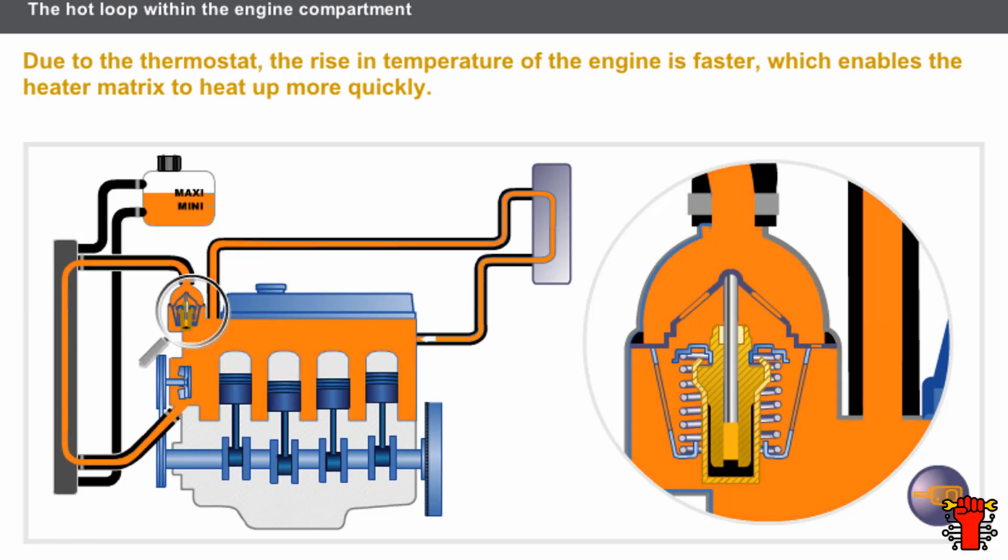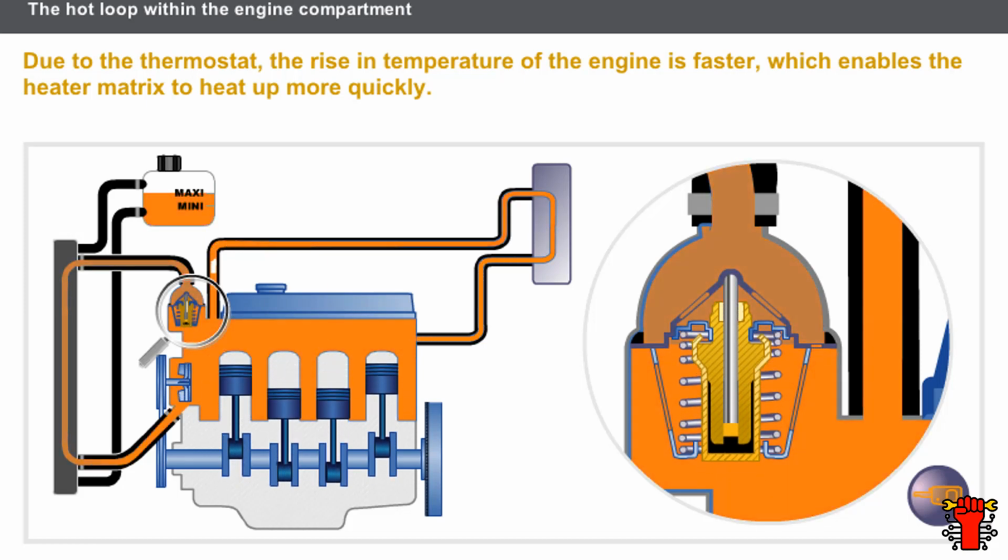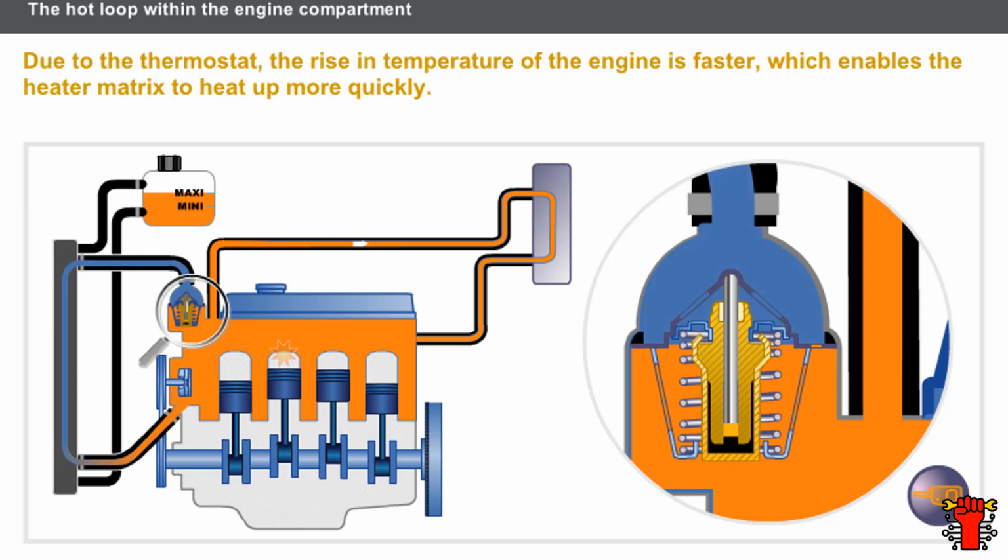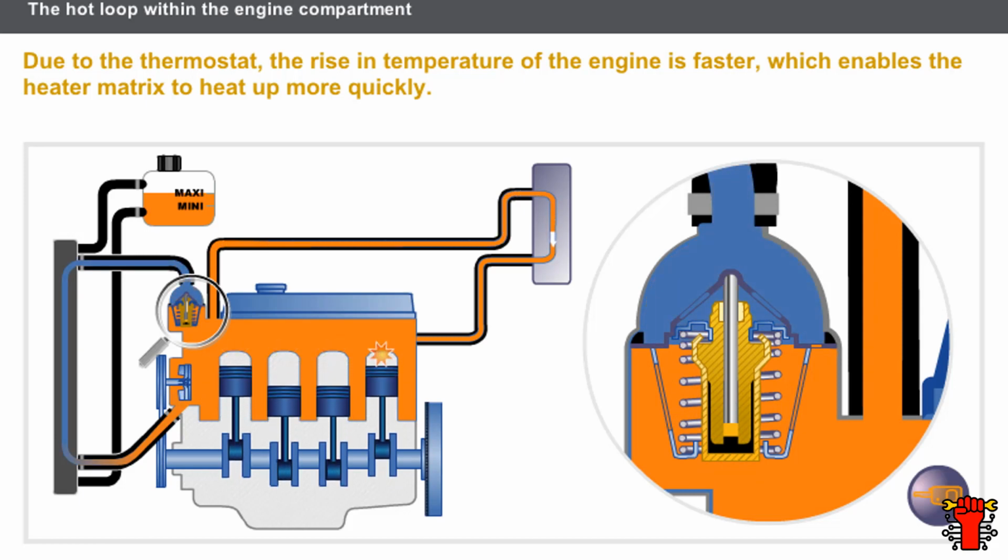When the temperature decreases, the spring brings back the capsule and the valve returns to the closed position. Due to the thermostat, the rise in temperature of the engine and heater matrix is faster.